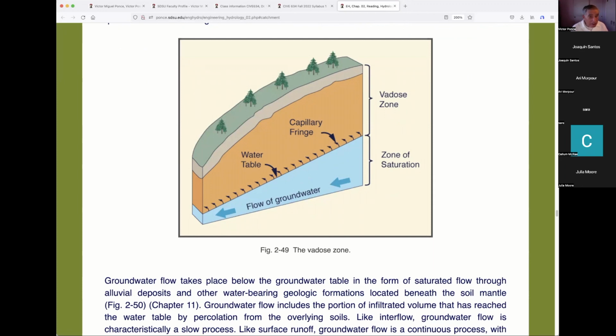And in arid areas, it typically doesn't rain enough. So the vegetation has to look for the groundwater. So you can see, therefore, according to Meinzer, and he's correct, that only in the places where the groundwater is within reach of the vegetation, and it'll depend on the types of vegetation. Some vegetation will send their roots to 10 feet, others to 20, 30, all the way up to 50 feet.